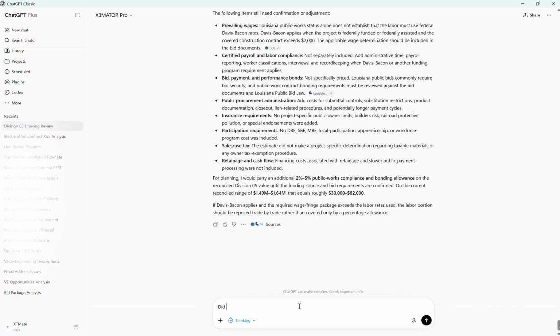Scroll through the structural steel category, HSS columns priced by the ton. The joist carried as an allowance pending the engineered schedule and labeled at a 5% fabrication and cutting allowance on the primary steel. Crane, lifts, and erection mobilization carried as its own lump sum instead of buried somewhere it cannot be checked.